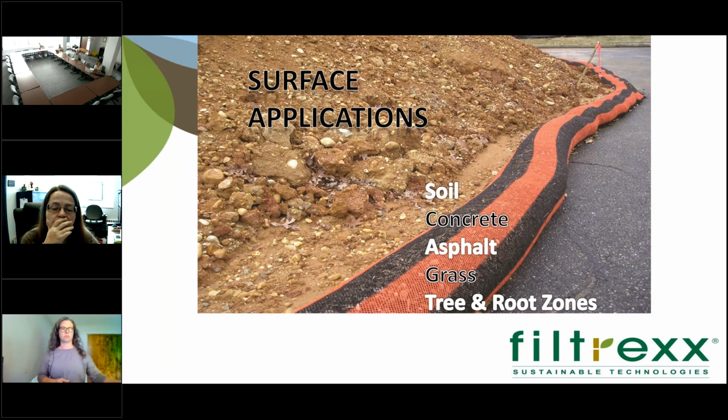The other benefit is you're not having to trench this material in like you would silt fence, so you're not digging and tearing up tree roots and possibly killing vegetation that way. So there's definitely some benefit to that.